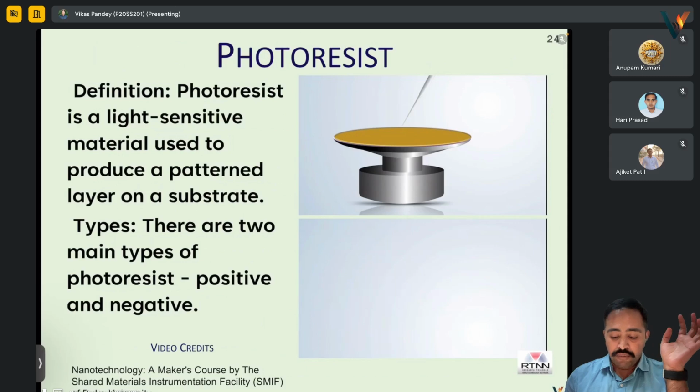Now, when we are coating this photoresist, it is a liquid, right? This liquid is spread over our wafer by spinning it at a speed, but it has to dry. We talked about the components of this resist: it has resin, then sensitizer, these things.